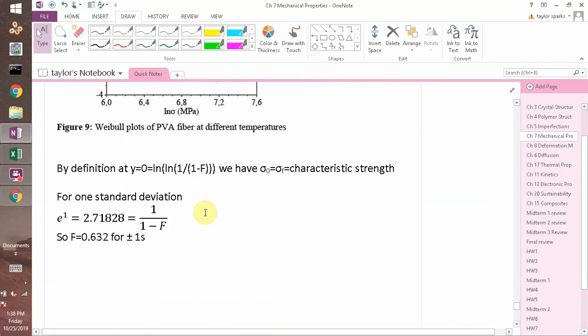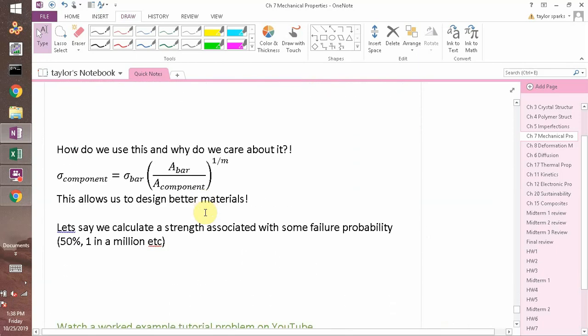Let's do, okay. So it's one thing to test a bunch of really small rubber bands. But what if your actual product is like fan belts on a car? Those are big rubber bands, right? Even if they're made of the exact same material, they aren't. But if they were, how would you go from your Weibull probabilistic failure predictions on a tiny little sample to something a lot bigger? Does it transfer? No, of course it won't.